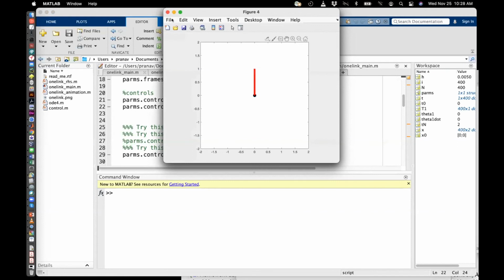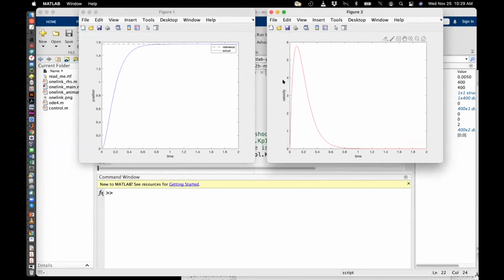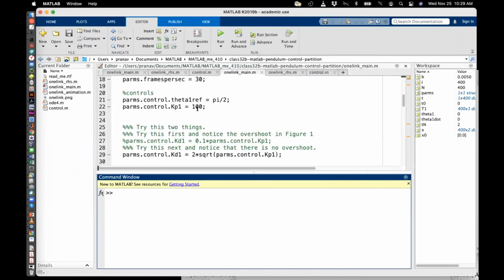Okay, it stopped. Let's close this. Okay, so here is the velocity, which is not so interesting as the position. And for position, you see that previously the best we could do with the PD control was 1.6 seconds. Here we've actually gone down to about 0.6 seconds, and we had to do almost zero tuning to get this, right? The only parameter we changed was Kp. Now we can actually make this go much faster than 0.6 or 0.7, I would say, by just ramping up this Kp.